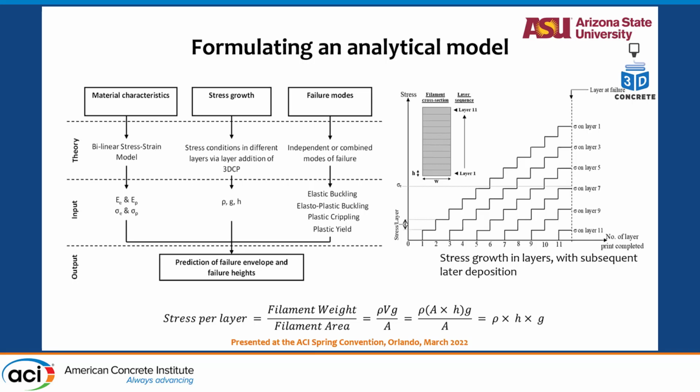And you can simplify it to a stepwise stress growth. Basically, the idea is that with adding layers, the stress on the bottom layer keeps increasing, and you use that stress development per layer as an indicator of what goes into the stress growth model. I'll talk to you about what happens next.